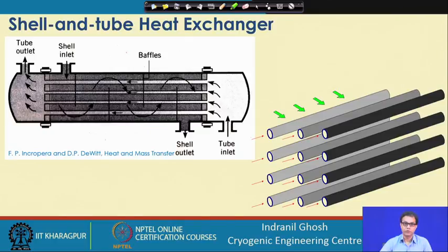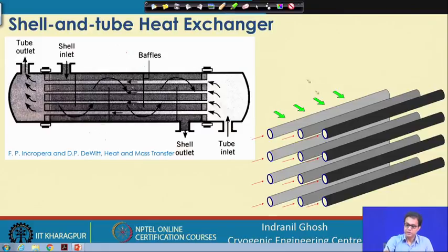about the tube side heat transfer coefficient, that is for the internal flow, and now we are trying to look for the external heat transfer coefficient, or the fluid flow when the fluid is flowing over the tube, and we now want to find out the heat transfer coefficient for that configuration. So, this is particularly valid or relevant for the fluid flow over the tubes in the shell side. So, there we have tried to find out the